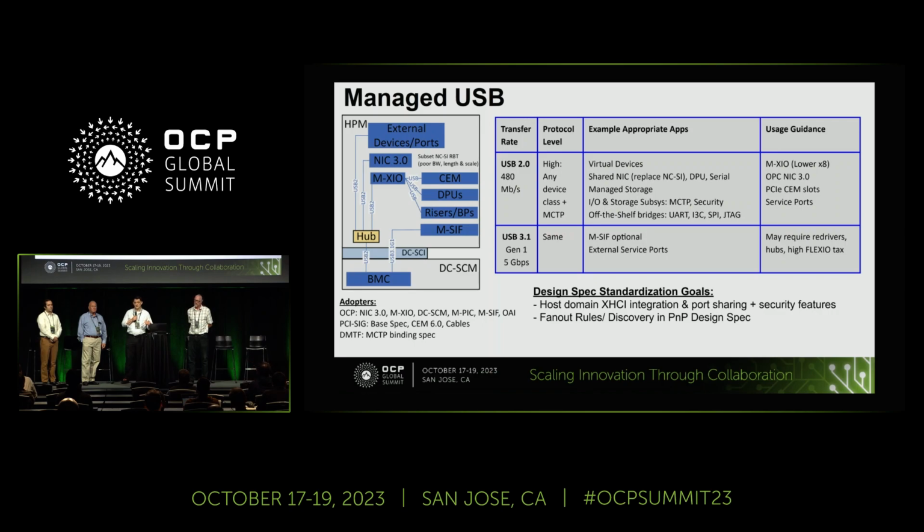The PCIe 6.0 spec, and we might ECN that back to 5.0, also has the ability to support USB as a FlexIO negotiation on the JTAG pins, which aren't used very often. So in production, that's another enabler that helps you do things like shared NIC, higher bandwidth MCTP to the targets, telemetry, and root of trust for update, measurement, and recovery is another good use case as well.